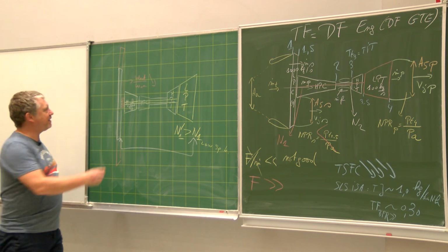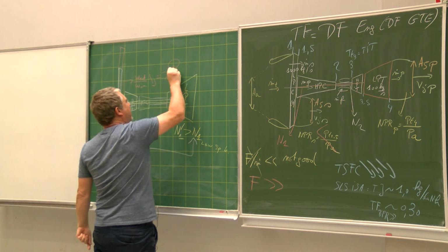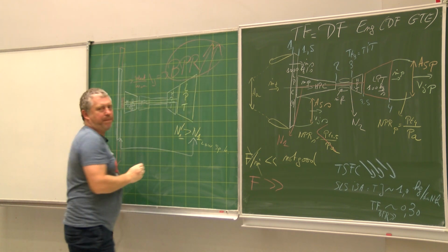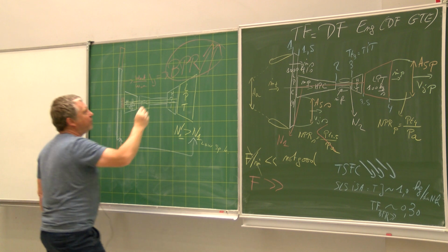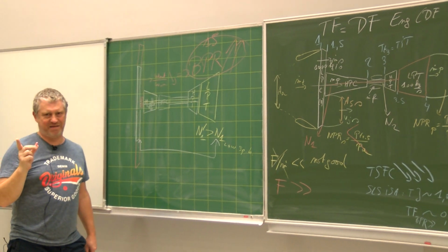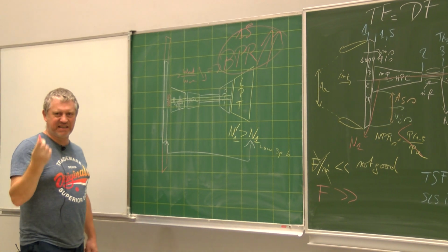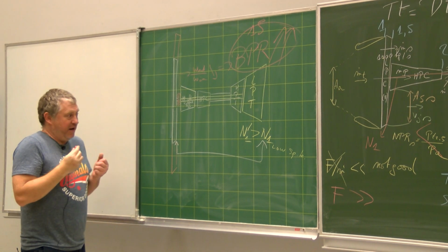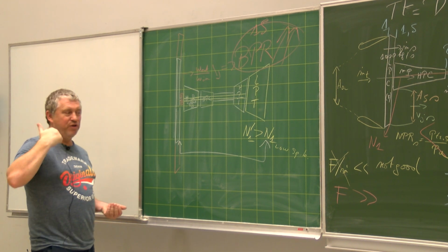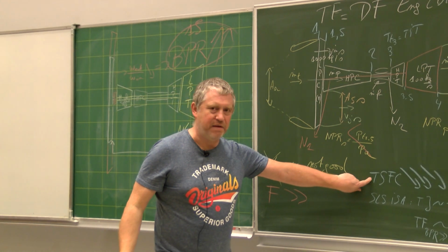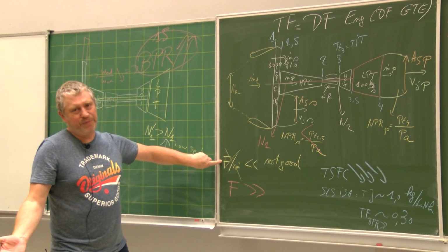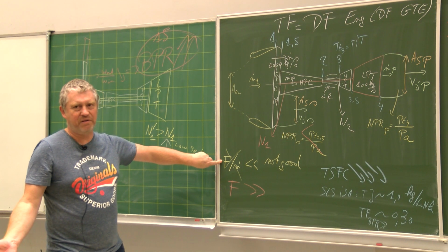Fan. And like this, you can increase our objective, the bypass ratio. Maybe here you can reach a bypass ratio of 15 at least. 15, 16, 17. And with the increase of the bypass ratio, of course, you decrease the TSFC. You increase the thrust, and you decrease, of course, the specific thrust.